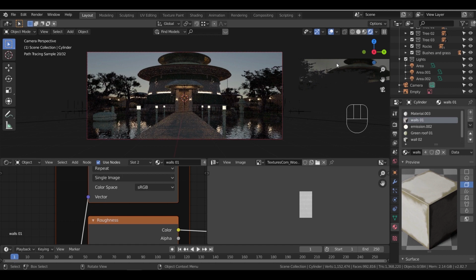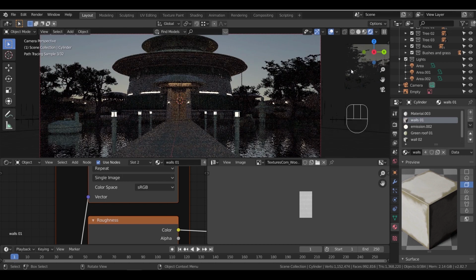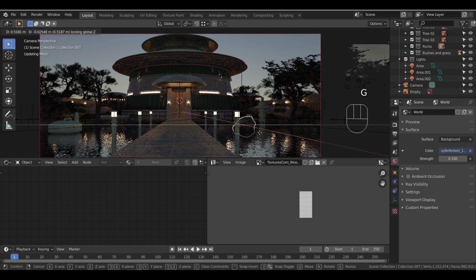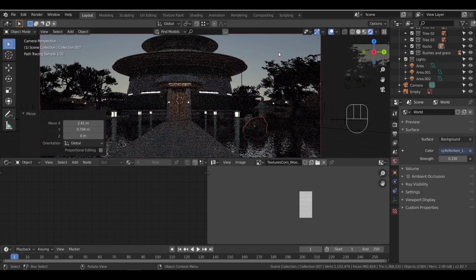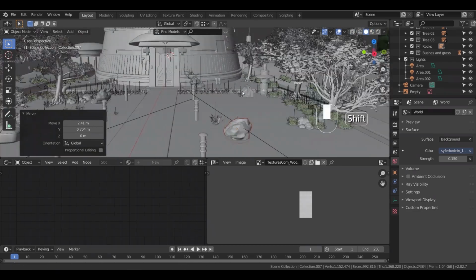Some important things to mention: if the HDRI is reflecting too much light on the roof, try to add a plane under the scene and scale it up to cover the horizon. If the green elements look too close to each other, delete them as we did before, and copy them again with bigger offset.